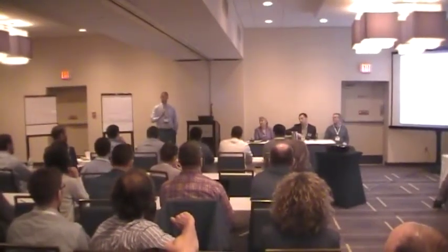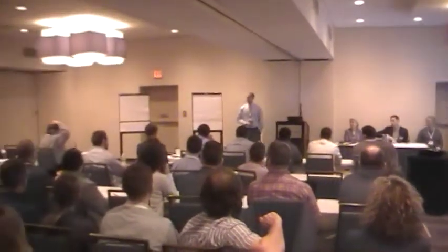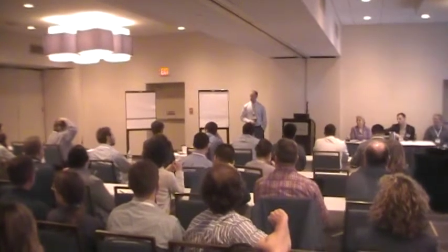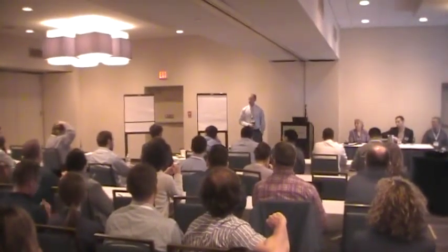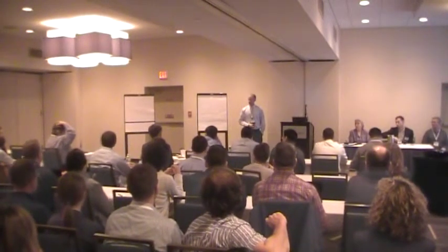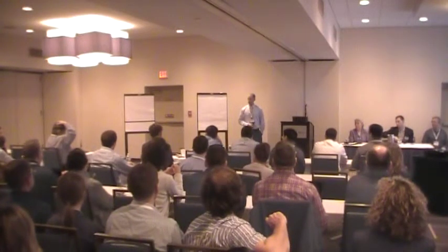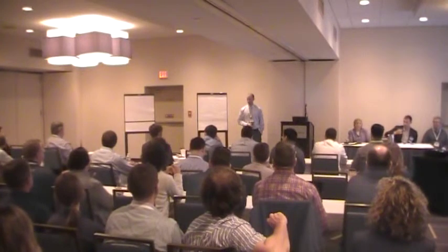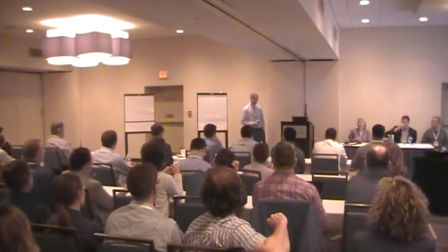Maybe one more question, and then I'll be done. I just wanted to add one thing, and I found this out the hard way a couple of times. When you are publishing off your desktop to ArcGIS Online, make sure that you only have the layer that you're going to want to use in your mobile device on your desktop. Correct. Because otherwise, you're pushing your whole desktop up. Very good. Yeah, you only want to have the one or two layers you're going to use.